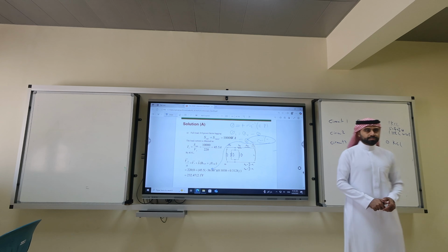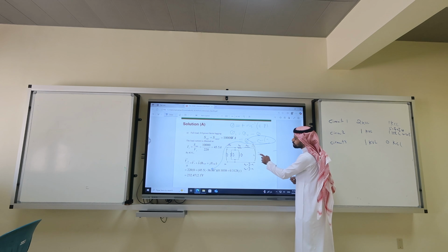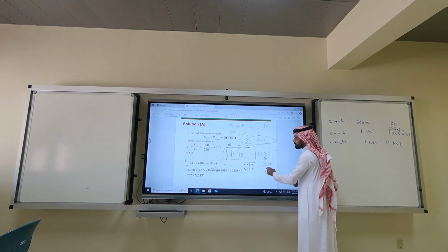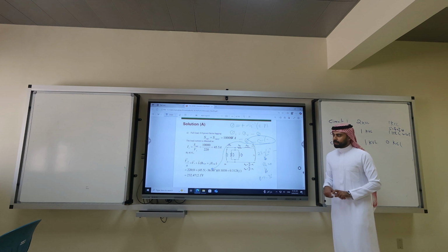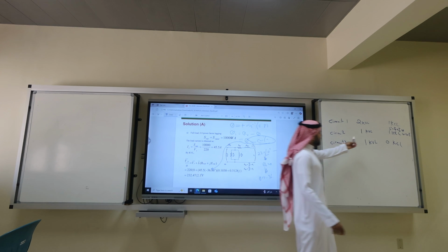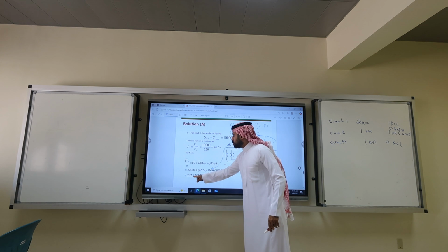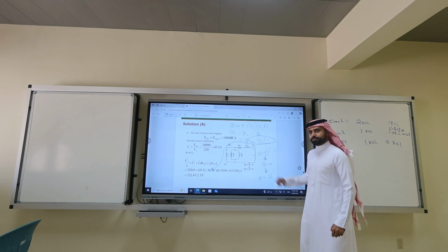Yes. Get it now? Because you're taking this 220 as a reference, theta V is 0. So this implies theta I is minus whatever, 36 degrees. Okay? So I'm doing the KVL, which is this KVL, under this equation, and I got 232 angle 2.1. So the voltage from Saudi Electricity Company is higher.